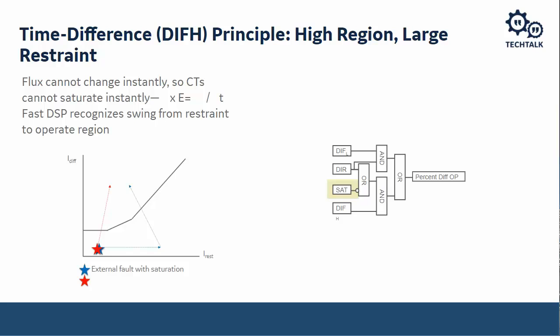For low impedance bus differentials, they typically do offer an unbiased operation. You need to be careful in setting that one because there is no bias. It's looking at strictly the differential current, so it could be fooled by this. So you need to set that one appropriately. Setting it too sensitive does not buy you additional protection.